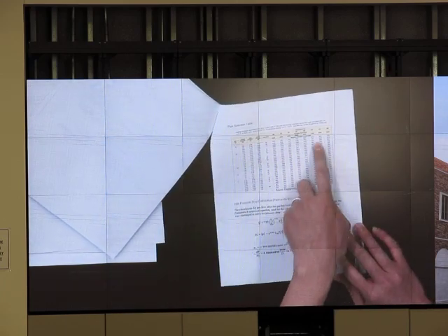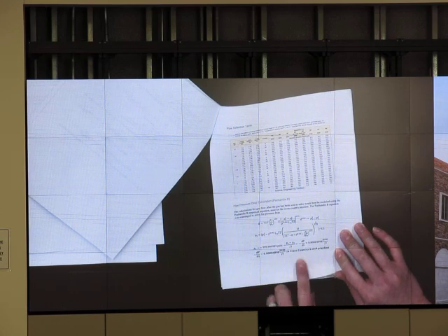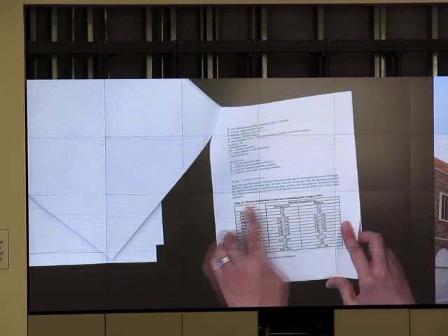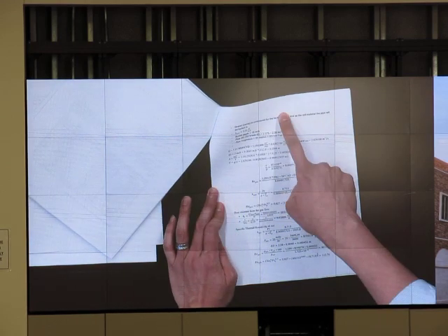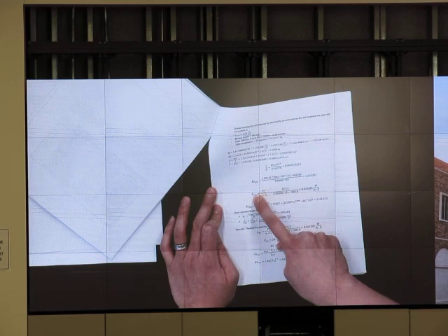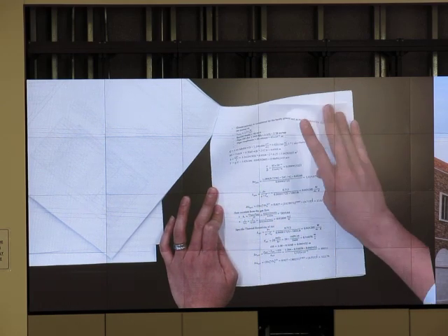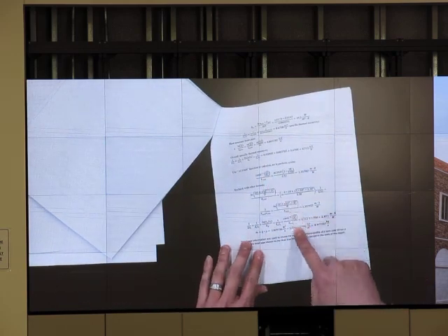Pipe selection, have a table for the pipe, pressure drop calculation, show the equation, show how to substitute the value, show how much they get. Okay, thermal conductivity, this is about the heat transfer consideration, and this is how they do the heat transfer: get epsilon over D, Reynolds number, thermal conductivity, Nusselt number, and so on. So the calculation is attached in the back, how they do all of that, how they substitute the value.